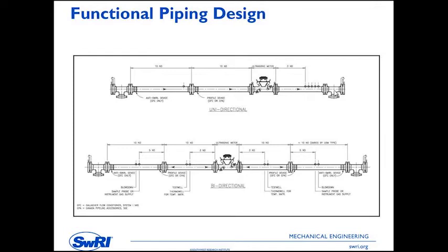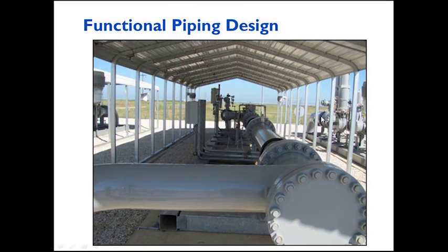But one of those considerations, and I hope you can see my cursor moving on the screen, are the end treatments that we put on the ultrasonic meters. And the reason I'm pointing this out is that most of the industry is aware that as gas quality is impacted and ultrasonic meters get dirty, their performance can change.